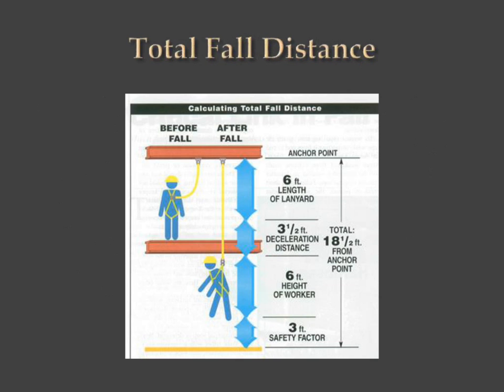All right, we were talking about fall protection in particular. Let's take a look at this particular slide. Many people, unfortunately, believe that when they put on a harness and a 6-foot lanyard with a shock absorber, they're going to fall 6 feet. Well, that is the farthest thing from the truth that you can imagine. This chart shows you what to do. And if you know this, and anybody that sells that equipment makes this available, it all depends upon where the anchorage point is and where your feet are.